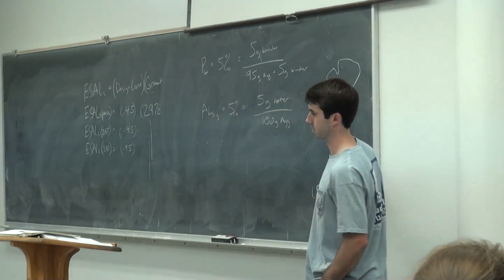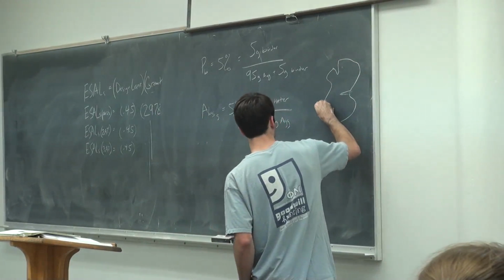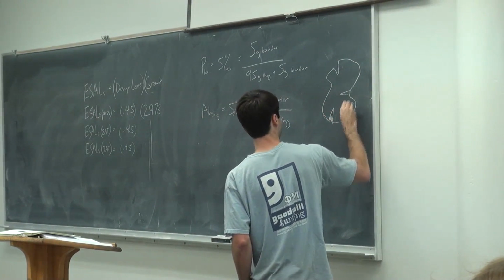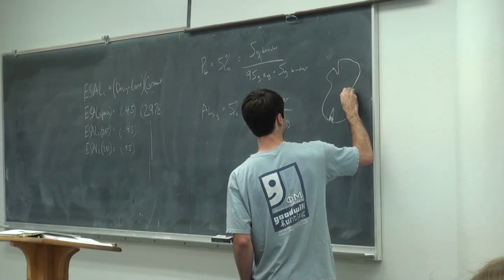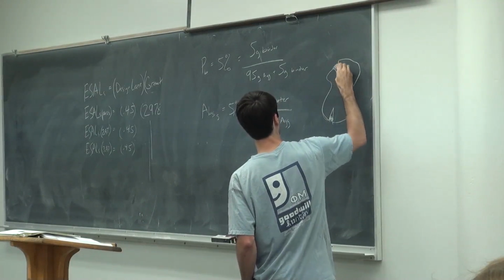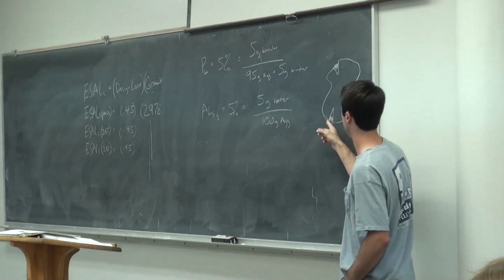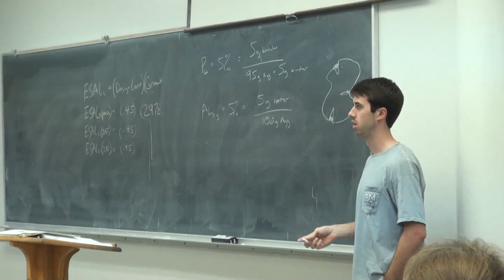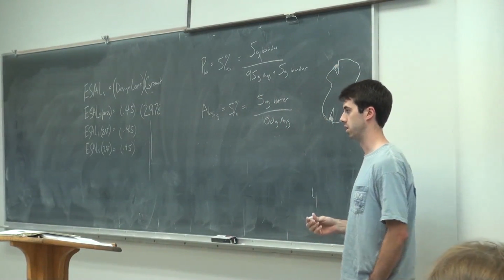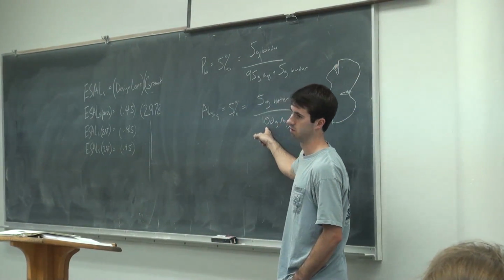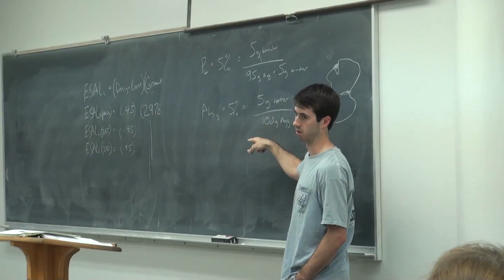So if you cook this thing in binder and some of it soaks in to where it kind of fills that little gap right there, now you got some of that binder absorbed. So the percent binder absorbed goes back to this standard where it's of the aggregate.